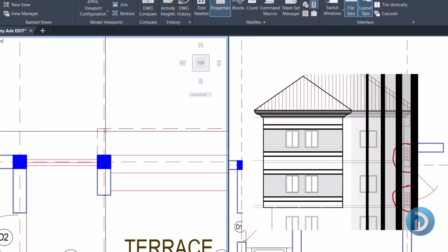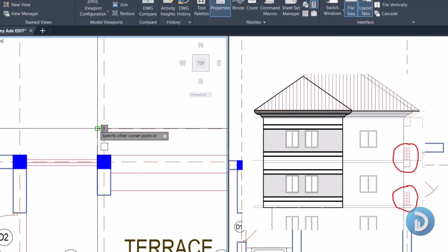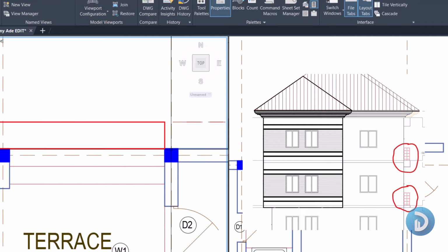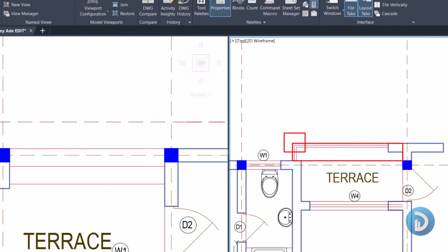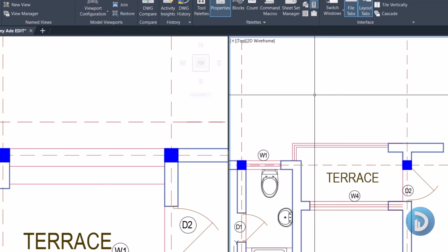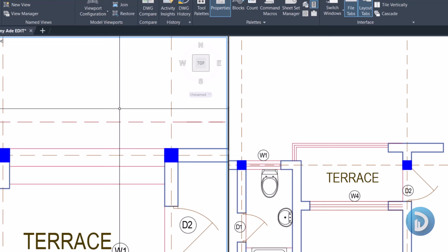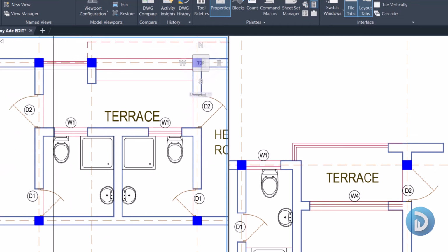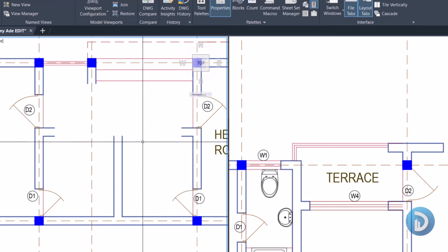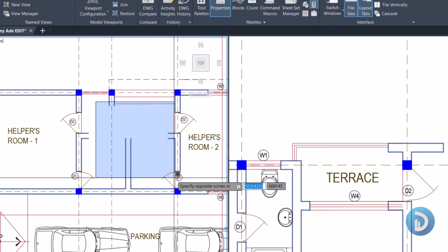little cantilevered beam that we'll introduce here, or we can decide to design this part as a fully cantilevered slab. Whichever works. Two structural engineers can have different structural arrangements, but these are the basics that guide you to creating a general arrangement. So what we'll do is we'll take out this entire part here, then we'll treat this as one panel, and we'll treat this other part as another panel.